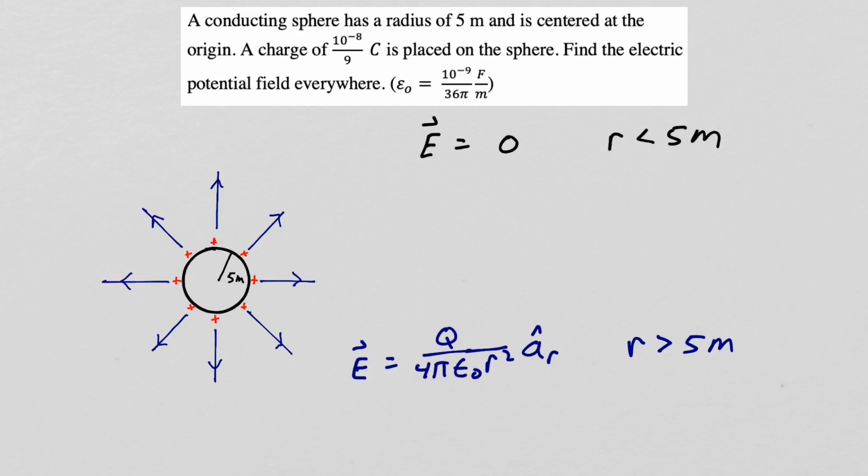Find your electric flux density field, and then divide by epsilon sub 0. Another thing I'd like to point out is keep the charge fixed, but reduce the radius. You would see that the electric field intensity outside the sphere would not change. And this is essentially the electric field intensity due to a point charge Q at the origin. So the field outside the sphere is no different than that of a point charge. If you're outside the sphere, you can't tell if you have a sphere of some radius with a charge Q on it or a point charge Q at the origin.